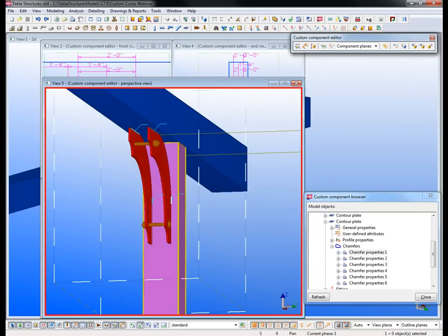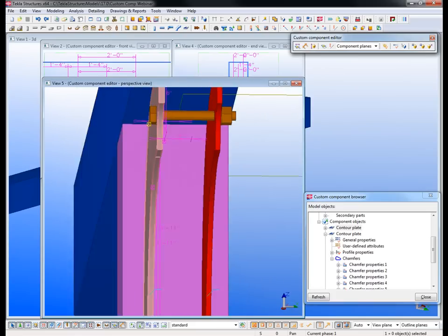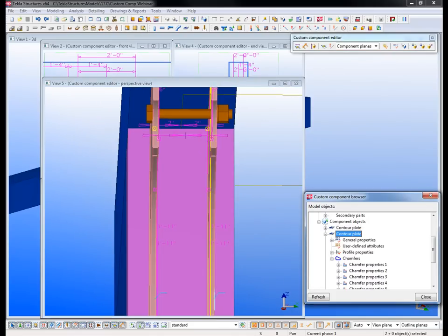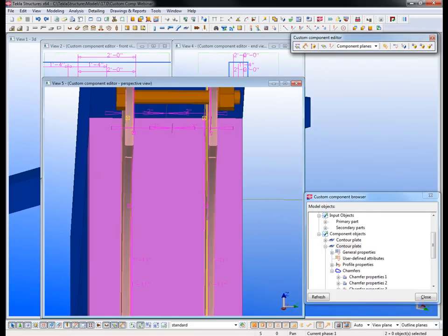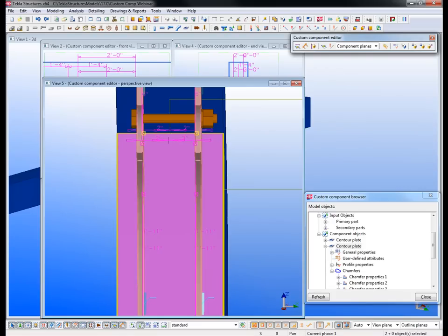Going along with that, the way that I did model these in is, you see when I highlight, I modeled these in as contour plates, is that we're going to define a variable for the user to define the spacing here. And I have my bindings on the inside, so that the bind is from this handle on the inside to the center of the column. So when we create our variable, we can just create an equal space, and it will just fluctuate that way.